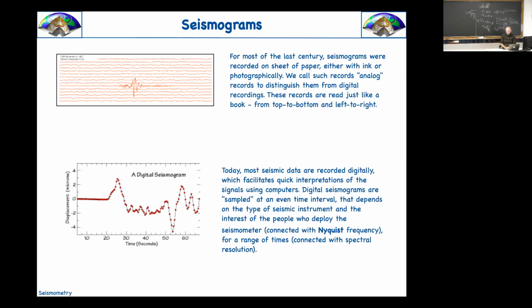So there was an idea here that is about sampling. That's why I want to spend a couple of minutes. I'm sure that you have already been studying this here, but just to be clear, I want to discuss a little bit with you about Nyquist frequency. Because now let's imagine that we have a signal. Let's imagine this is an amplitude. Maybe it's the ground motion, maybe it's displacement. Okay, we have something like that. And in nature, this x of t has infinite values. It's a continuous function of time, of course.